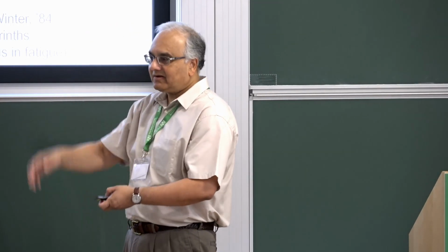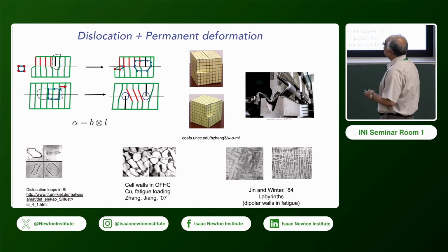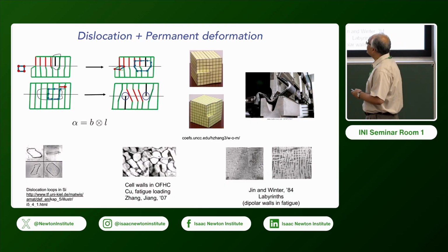You take the loads off, it doesn't go back to its original shape, and that has to do with the fact that there is periodicity in the lattice. You might think of that situation as this being a slip plane, and this business of not going back has to do with these atoms here changing their neighbors. So something that was here has now moved over here, its nearest neighbor will be here, and so on and so forth. This is a slip plane.